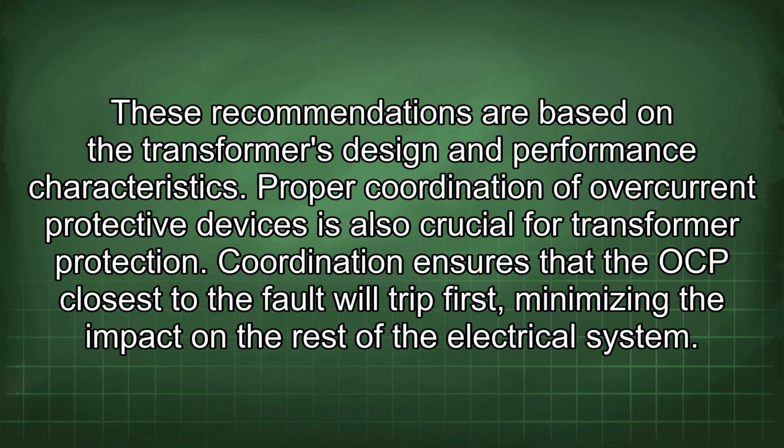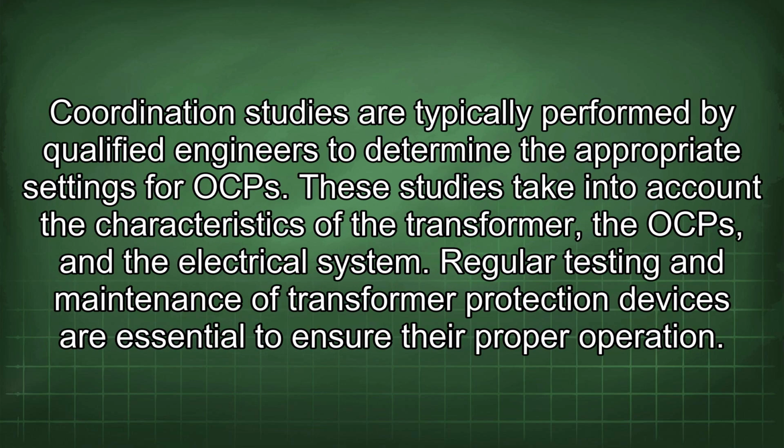Proper coordination of overcurrent protective devices is also crucial for transformer protection. Coordination ensures that the OCP closest to the fault will trip first, minimizing the impact on the rest of the electrical system. Coordination studies are typically performed by qualified engineers to determine the appropriate settings for OCP. These studies take into account the characteristics of the transformer, the OCP, and the electrical system.